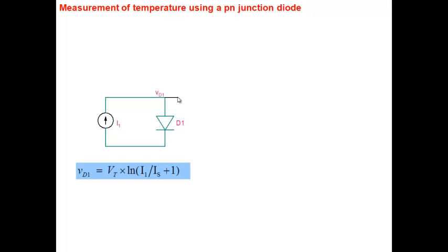But again, it's also a more expensive solution. A microcontroller is a digital circuit. I have to use an analog to digital converter. I have a memory. It's a slightly more complicated solution, but you can easily do it. But what would be a simpler way of doing it? I want my voltage to be proportional only to temperature and not have this nonlinearity. What do I do? How do I get rid of this? Huh? Another diode. Okay, then?